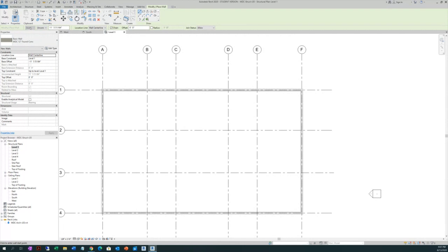So we're over here on the option bar. Okay, yes, it's there, but no, it's unconnected. You are going to go to the top of the footing, correct? So in other words, over here on the top is going to be the location line. You are going to click and say, no, it's my core center line. The core center line of that concrete wall or foundation wall, okay?